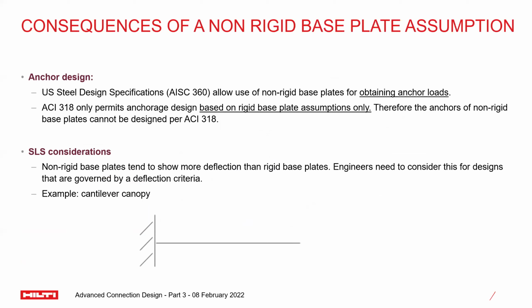Before we deep dive into the details of nonlinear base plate analysis using FEM or FEA, it is imperative that we look into some of the consequences of using the non-rigid assumption. One major consequence is the lack of model code compliance. Okay, let's understand this. Eurocodes or US steel design model codes based on AISC allow the use of nonlinear or non-rigid methods for designing base plates in order to obtain the forces on the anchors. So the base plate is part of the load path, and force distribution to the anchors takes place using finite element analysis. Once we have the forces on the anchors,